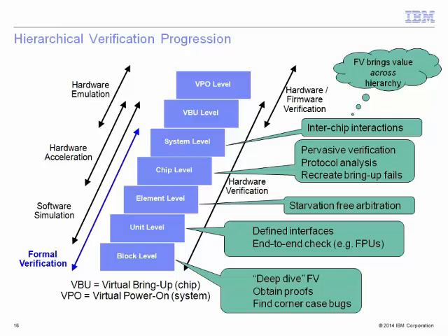At the system level, it's basically used for inter-chip interaction verification. There, of course, we would again have abstractions or behavioral models for all the chip levels, and we would be verifying whether some register writes or some kind of interaction protocols are working properly in place or not.